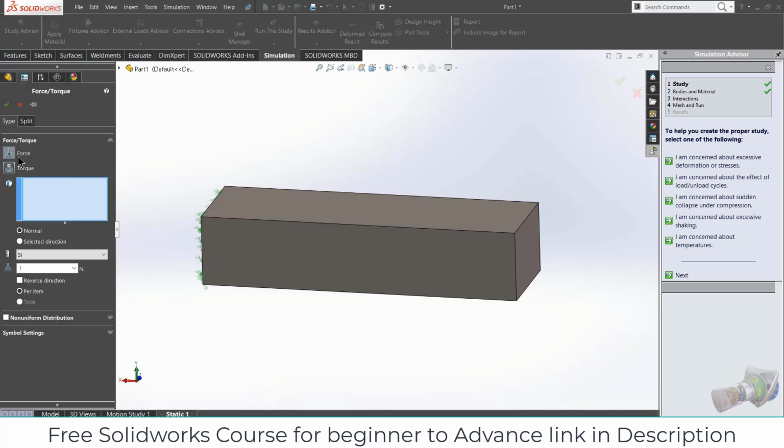Now, first thing it will ask, what is the face, edge or vertex? For example, here you can see I'm just moving my mouse here and it automatically selected the face. If I select the edges, it automatically selects the edge, as per my requirement. So as I said, it is a cantilever beam. So I will select this edge.